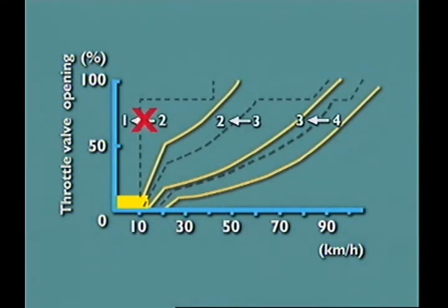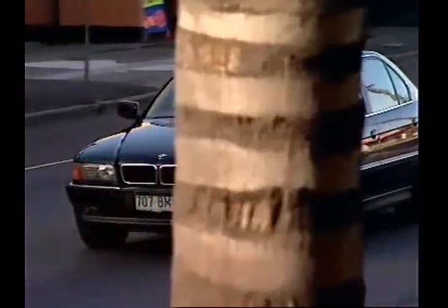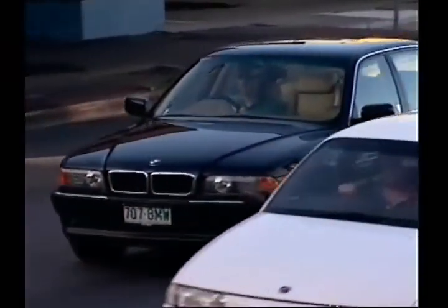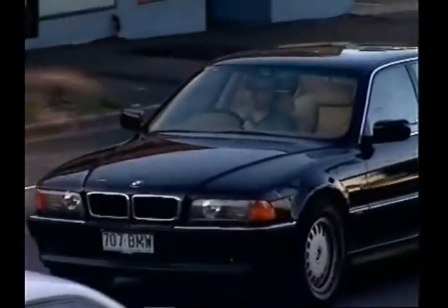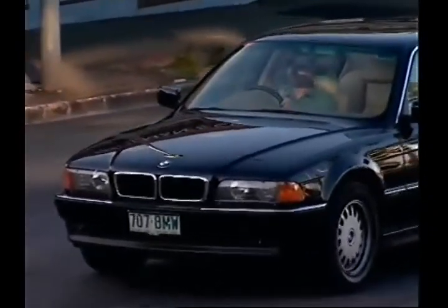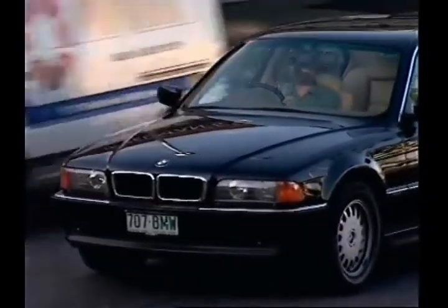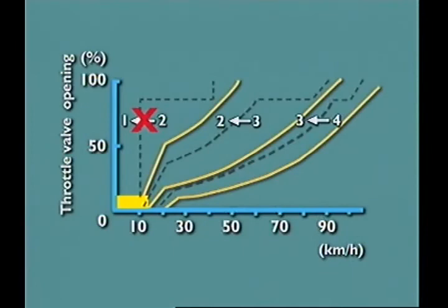This prevents shifting down to first gear. That makes progress smoother, lowers fuel consumption, and reduces any tendency to creep forward from a standstill. When the preset load speed range is exceeded, first gear is no longer inhibited.